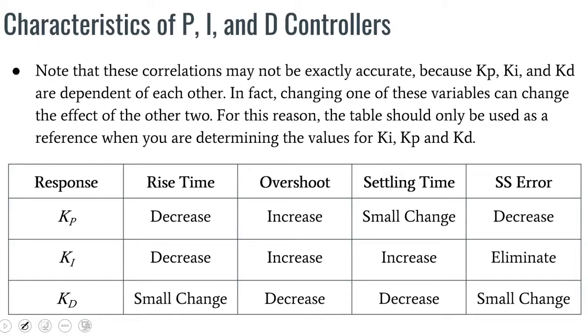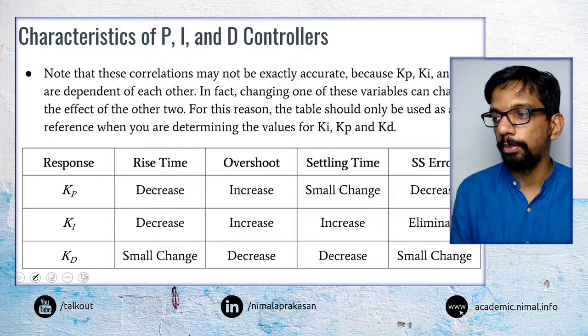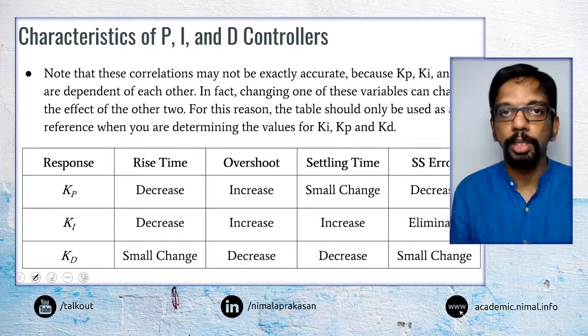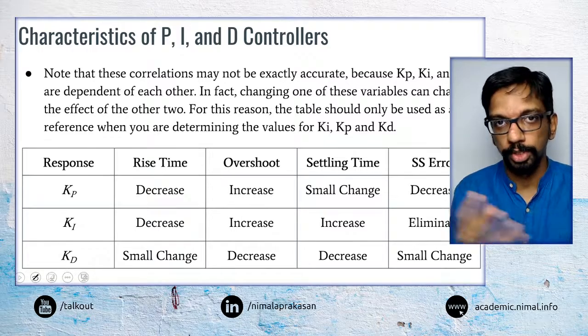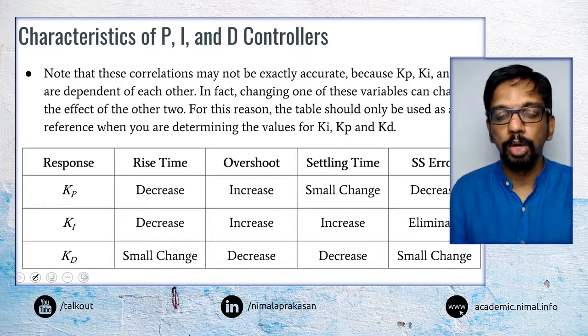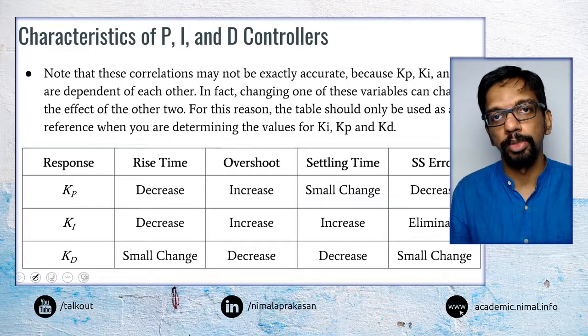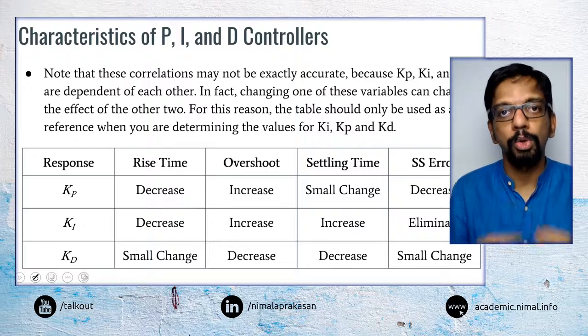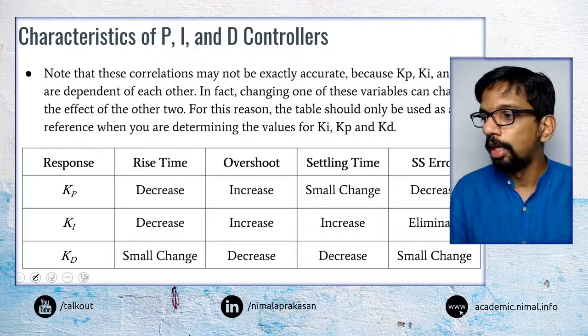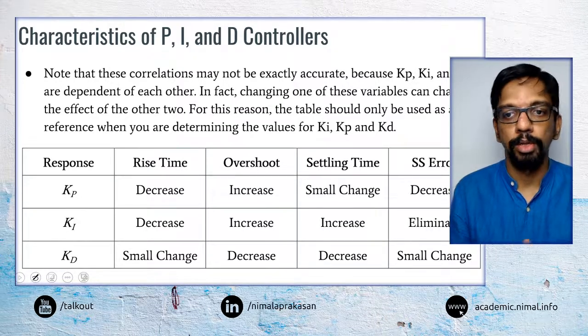So when considering the PID controllers, one of the main things that you will have to figure out and configure is the K values. When you are implementing these as part of your projects, the basic PID controller, the functions, the equations, the algorithms are fairly the same for all use cases. But the K values are the ones that you will have to figure out depending on what you expect your system to do. You will have to tune and find the particular suitable K values for your use case. So that is something that you will have to implement in your project situation.